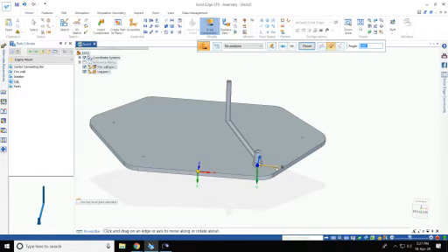I think you can't move it on x-axis. If you want to move it on your y-axis, you can move it on your y-axis. That is the only degree of freedom that is left so far. Z-axis not possible, x-axis not possible, because it has made the contact surface. The only possible axis is your y-axis. Keep it at an angle that you desire. The more familiar, more convenient angle for me to keep it is something like this and not something like this.